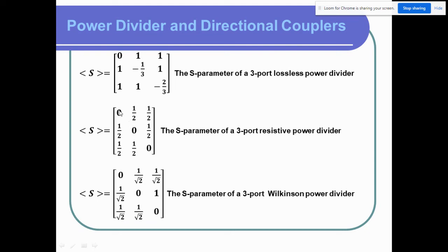However, it solved the issue of the reflection, but the power will be 1/4 at the two junctions, because this is voltage. Voltage usually we convert into power and we need to square it, isn't it? So it means 1/4. When we try to split it, it gives us some losses inside the power divider.